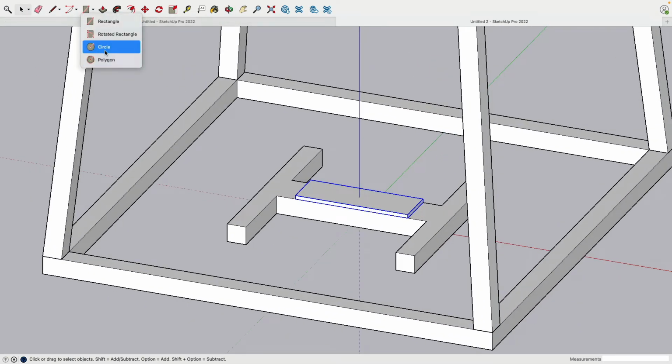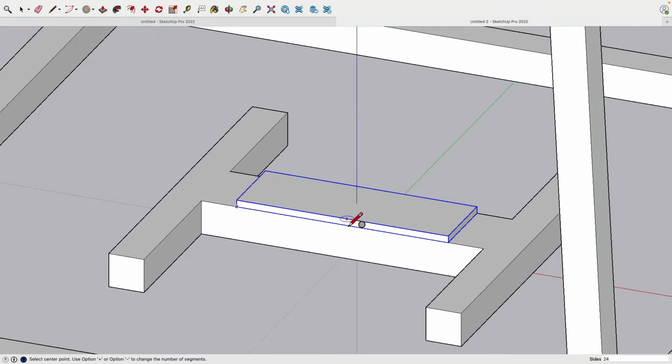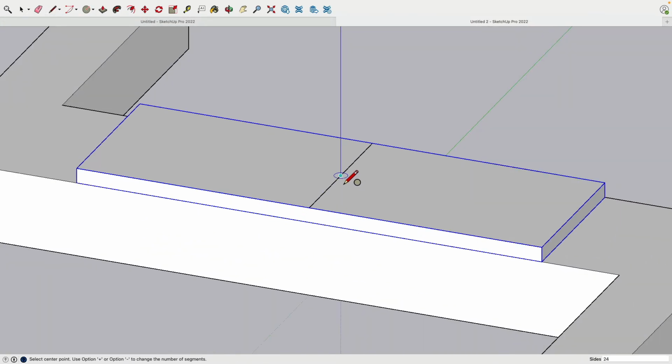Then let's switch to circle. So, where's this? So here's the midpoint. Yeah, but where's the midpoint? Right there, no? Sometimes snapping works, sometimes it doesn't. So what about we just draw a line edge to edge, because this way then we can find a midpoint. 0.5 inch for the radius. Oh, this is way too big. So 0.25. So we have a half inch diameter. These helper lines now we can remove.